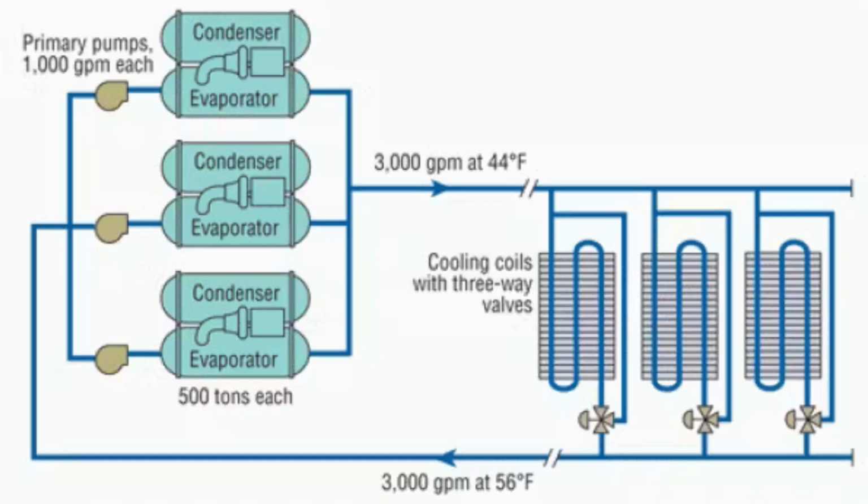Medium systems, 3 to 5 chillers, require smart sequencing. Designers decide between equal runtime rotation and preferential loading of the most efficient units. Variable primary flow and series arrangements become more common. Digital control systems coordinate pumps, valves, and chillers for stable operation.